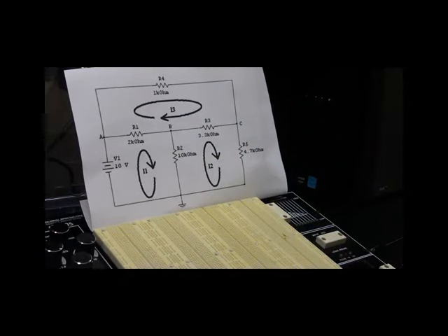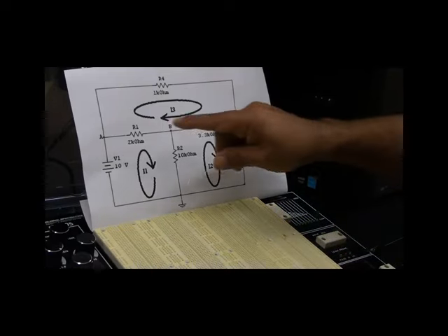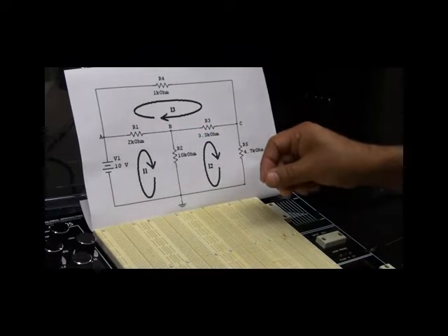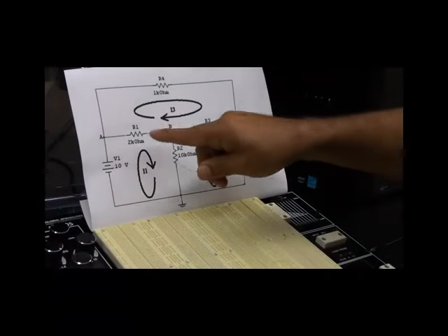The reason is that when you look at the circuit for troubleshooting, you can simply compare it to your circuit, and the topology is going to tell you if you have implemented it right or wrong. So you don't have to find out one by one if R1 was connected to R2 or R3. This is very important in troubleshooting, so always follow the structure of the circuit diagram and select the same topology for implementation. I'm going to start from R1, but does it matter? It really doesn't matter. You can start from anything. So I start from R1.